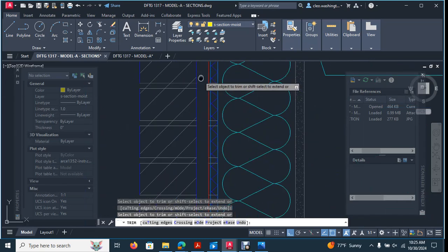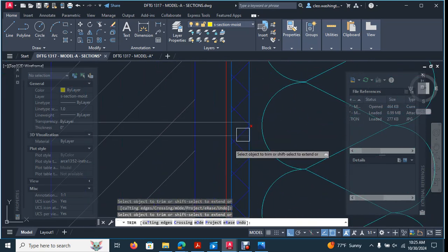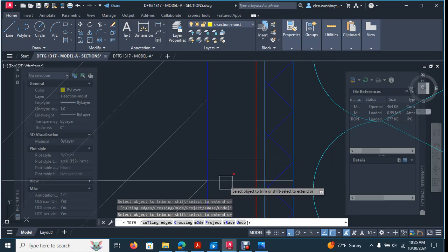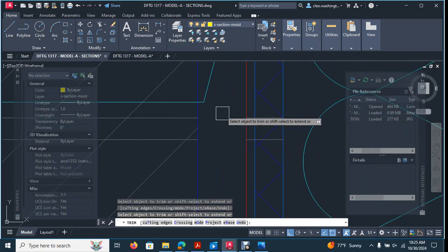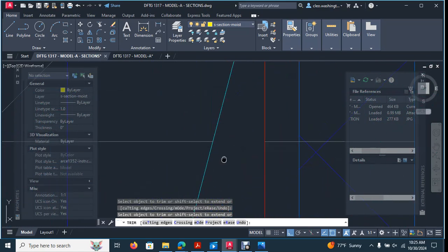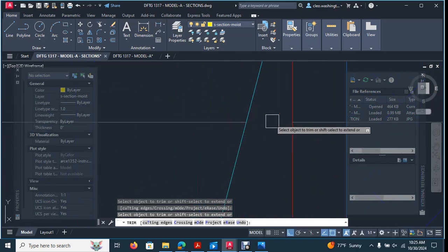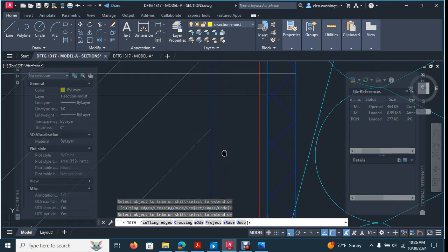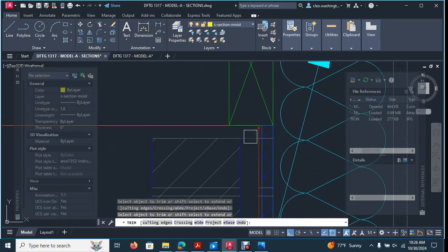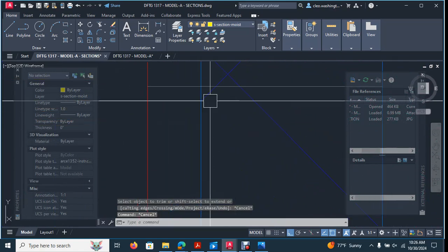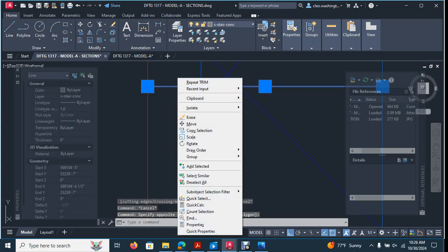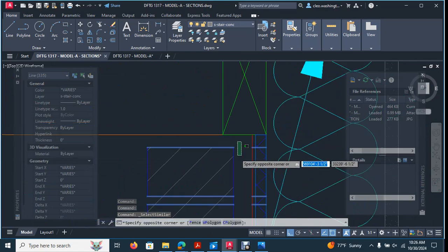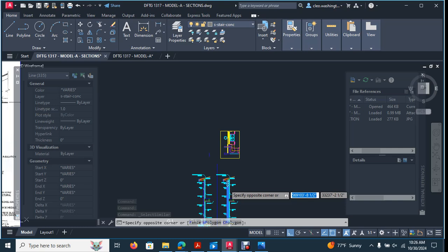This is called airspace between the brick and the exterior sheathing. Typically it goes for 1 inch to 1.5 inches. It just depends on the contractor and what they actually constructed. But typically I'll draw mine in at 1.5 inches. The more airspace, the better. And again, the red line, that's your waterproofing membrane. Okay, there you go. So now select this guy, right click, go to select similar. And now you want to hold down shift and you want to deselect all of these other ones.